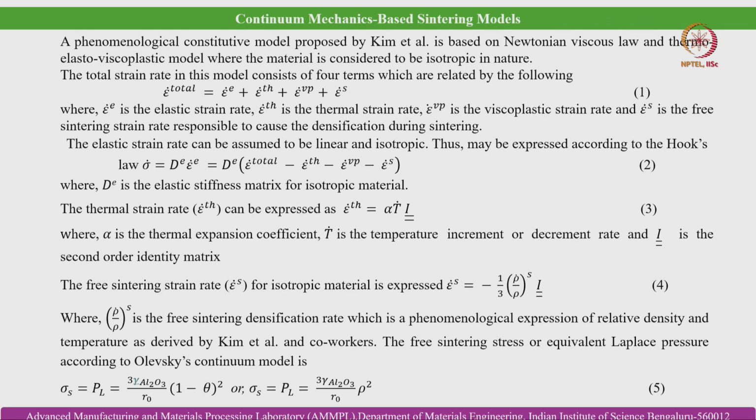sintering model can be effective to understand the sintering kinetics and to optimize the sintering densification by adjusting the temperature and time and also the heating rate. So, all those variables impact the microstructure and also the densification and shrinkage in case of sintering of the metal injection molded or ceramic injection molded green compact.